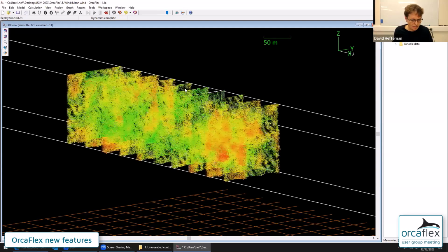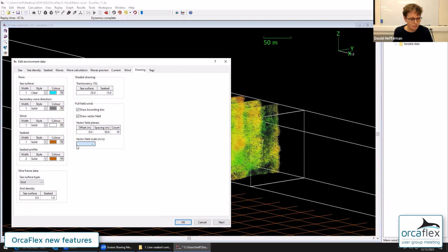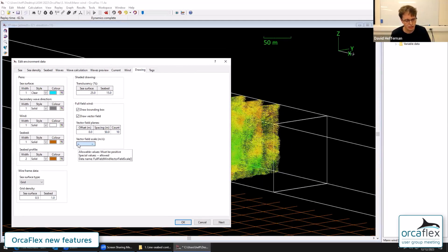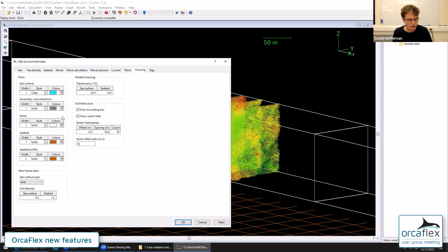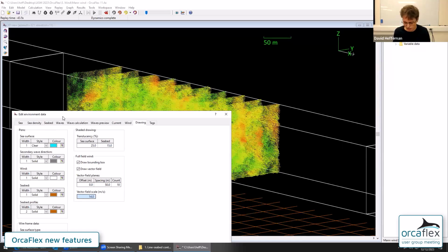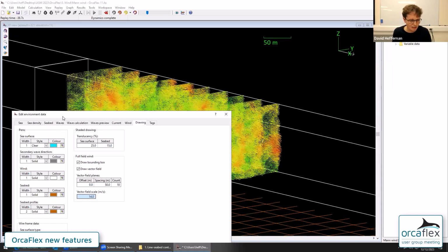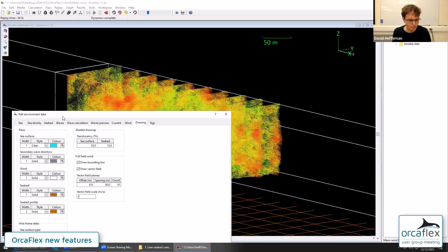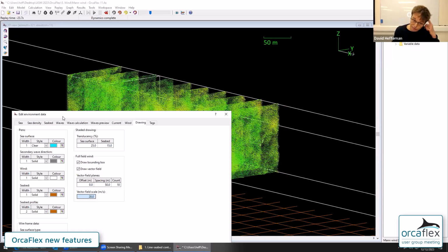You can change the scale, which affects the color and the length of the arrows. The tilde means use the mean wind speed. So if I put in a value of 14, it shouldn't change anything because that is the true mean wind speed. Then if I change the value, you can customize how this works out. I'm going to go with a value of 12.